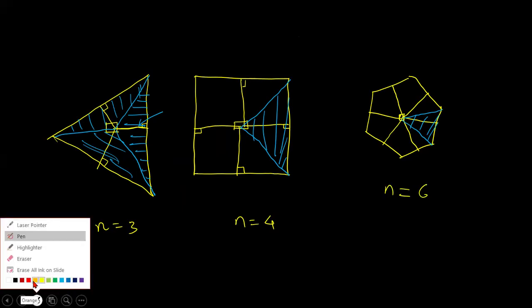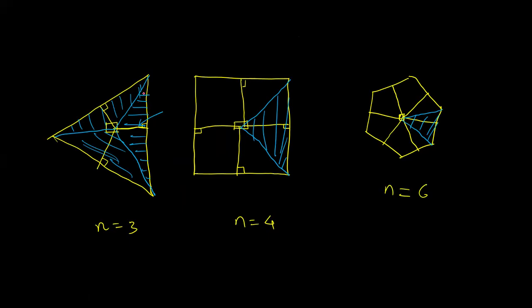So you can notice here that in the triangle case, this is the boundary of the service area served by the individual feeder. There are three feeders in total. So the total angle subtended at the substation, which is basically 360 degrees or 2 pi radians, is divided into three components. So this one, that one, and that one.